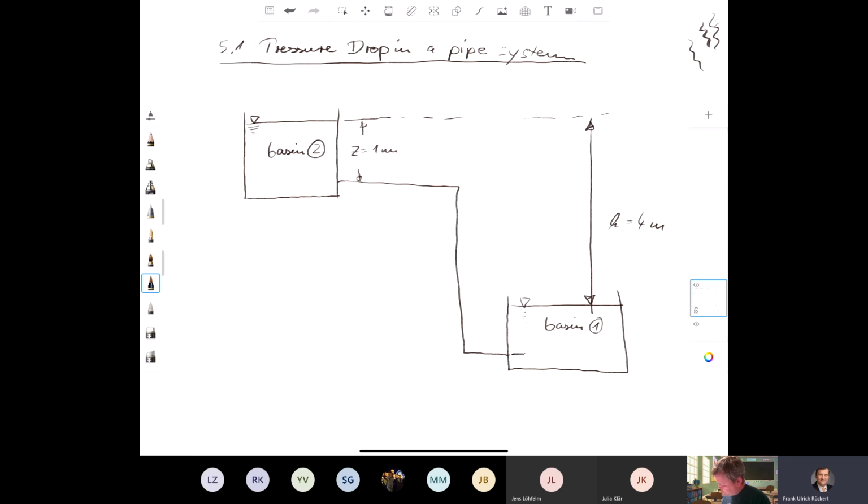And we have the velocity here C1. Okay. And first step we have to do, we have to formulate our Bernoulli's law. Yeah, and we have to take into account also the losses. But before we start with the calculation of the losses, we will just say, okay, the losses might be 0, we have no losses, and we make the first calculation without any losses.